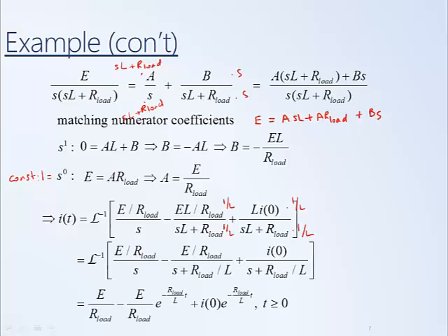So performing that inverse Laplace transform, here's our e to the minus AT multiplying a constant. This is a step, but since we don't consider our function to begin until t equals 0, we can also just write it as a constant starting at t equals 0. So this is the behavior of the current through our circuit, or through the inductor, once the switch is opened.